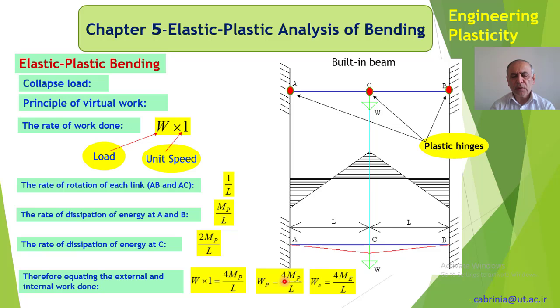But if you use the plastic capacity, you can go much further, maybe twice the load or more, and still the beam stands and it does not fail. And this value of Mp is the fully plastic moment, but we could use a moment less than this but much higher than this in order to use the plastic capacity of the beam to carry out more load.